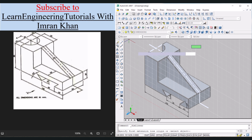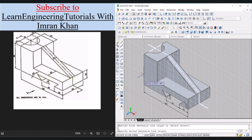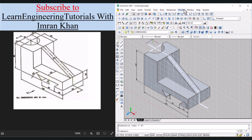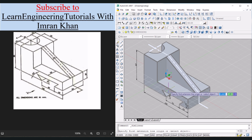Click on this linear option, select this endpoint by zooming in and then select the corresponding perpendicular point, move the cursor away and click. Now we have to change the face, so click on face UCS, select this face, click on accept, click on this linear icon, click anywhere and click on opposite perpendicular point and click again.